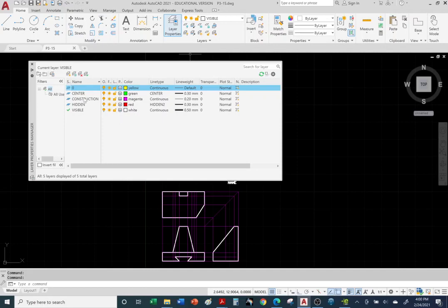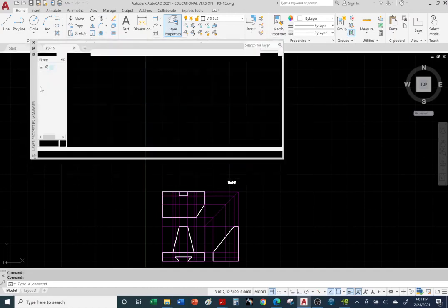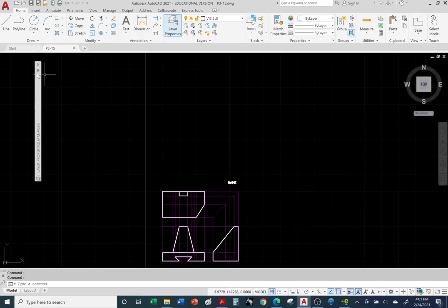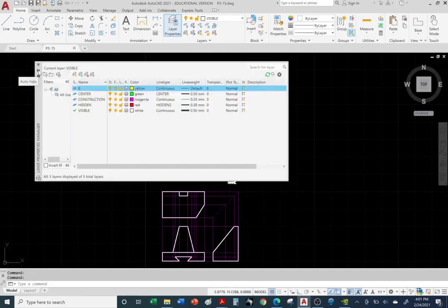And by the way, I forgot to mention construction lines. So construction lines are temporary lines. So here what you see in magenta, go ahead and increase this. So I'm using magenta for construction lines or temporary lines. You can go with no thickness, or I chose 20, but I should just leave it at default at 0, but you'll still be able to see them. And I chose continuous solid lines, and that's what you see here in magenta. So these are guidelines.